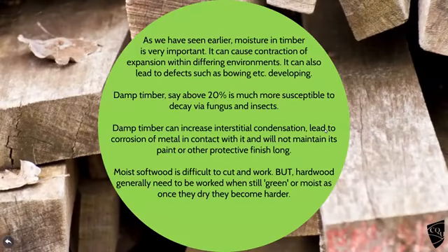Moisture, as it's a natural material, it will take in moisture from the atmosphere. If it's in contact with the damp ground or damp surface, capillary action will bring it into the cells and structure of the timber. So it's important. If timber gets too dry, it will actually start to split. If it gets too damp, it'll actually begin to bend, curl and warp. It expands and contracts. So timber will be a slightly different size in the middle of the summer in a tropical area, like North Queensland, than it will be down south where it's drier, it's not as humid.